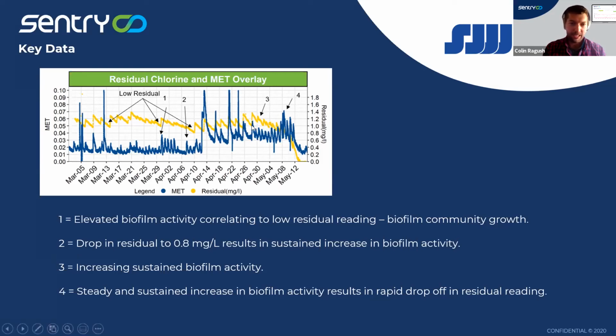And this presents a problem for the system, specifically since San Jose is using chloramines. They know that the development of nitrifying conditions is a problem. So we knew we'd developed something, and then in early May, we started to see a lot of rapid changes in activity. And that's unusual. And that tells us that something's devolving or unstable inside this biology. And it turns out what that appears to have been is one of these nitrification events. So when they get nitrification, they get rapid depletion of the residuals. And sure enough, that's exactly what we saw in this case.